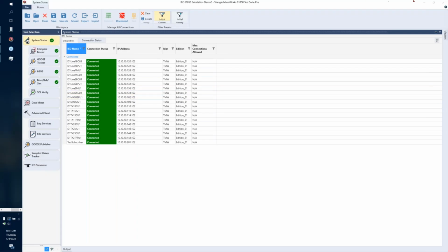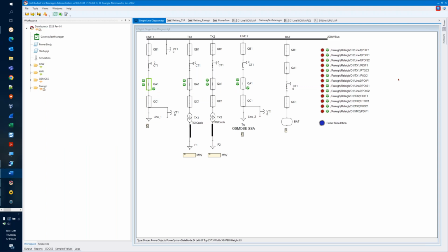All right, thanks, Christoph. So just to reiterate, one of the big benefits of the 61850 engineering process that Christoph's been talking about is that it results in machine readable documentation of the substation. And that is, of course, in the form of the SCD file or substation or system configuration description.